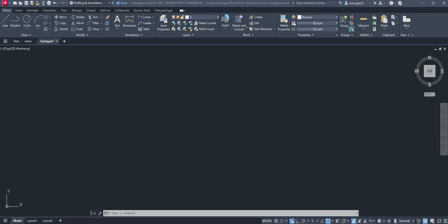That's why you're seeing a tiny thin line and then a thick line. Just by looking at the icon, you can say which one is what. But they're all going by layer. I always think of by layer: color by layer, line weight by layer, and line types we set up by layer.